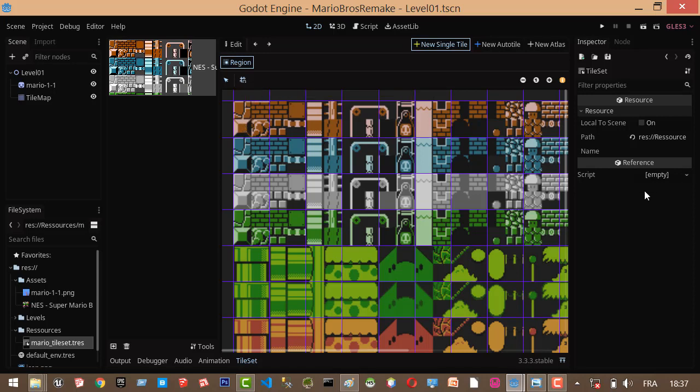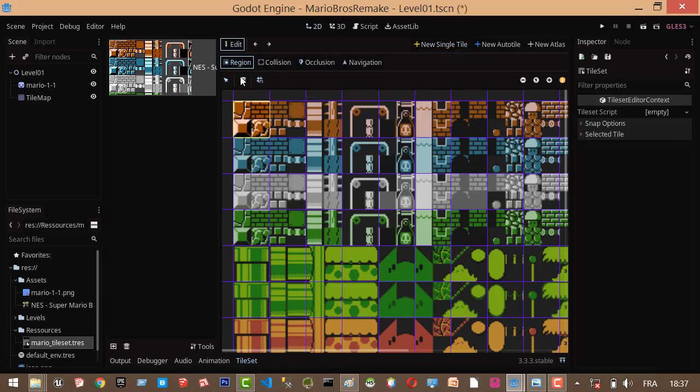And by default, when you start a new tile, you can have the snap option. You can't have it before, so you have to click first on the asset, then you do have the snap option. And by default you have a step of 32 by 32, so we're going to change it to the good size, and the good size is 16 by 16. And you see we do have our tile made and correct.